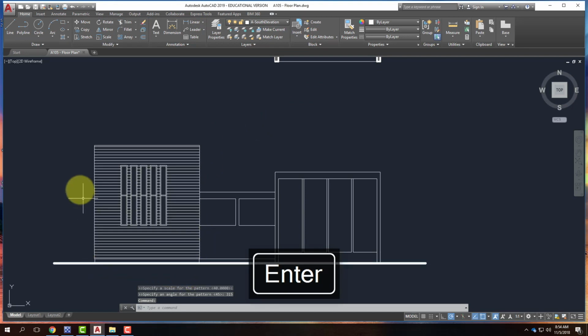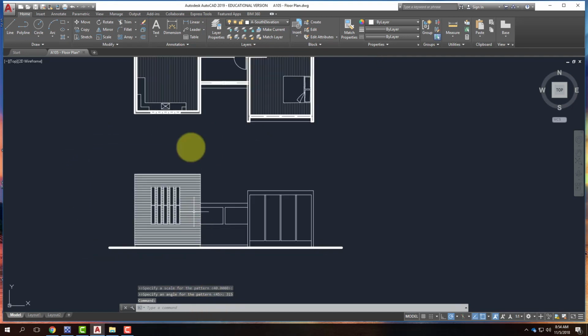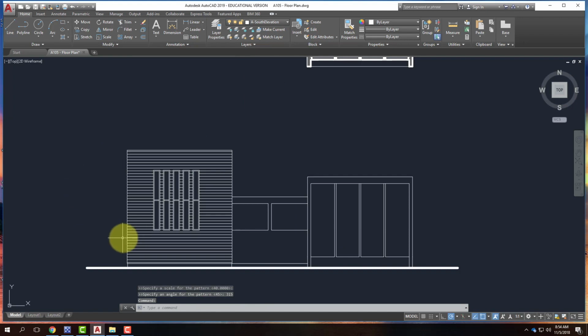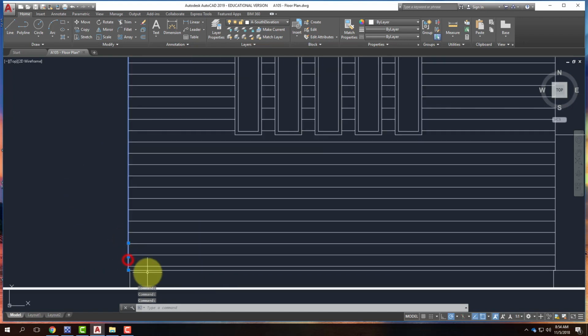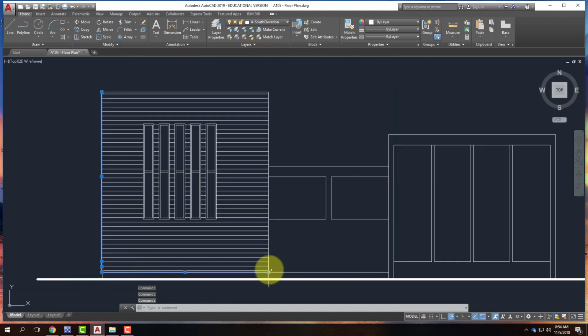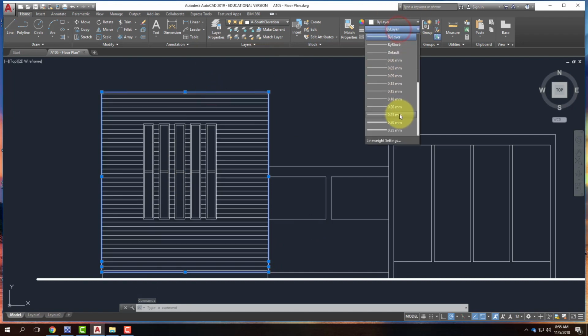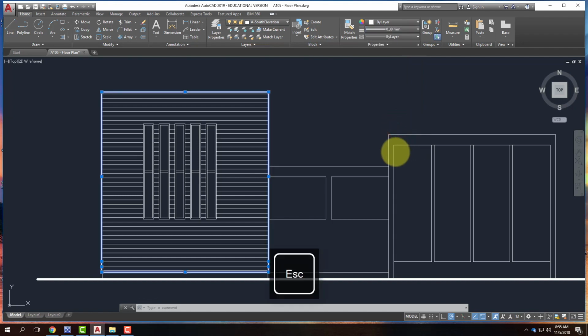I also want to go through and change my lines. Things that come toward me need to be bolder. So in elevation form, I actually recommend just going around and assigning line weights manually, because typically it doesn't fall cleanly into having everything on an elevation layer and that's it. So I would go through and say, this is coming toward me, therefore it should be maybe 0.3.